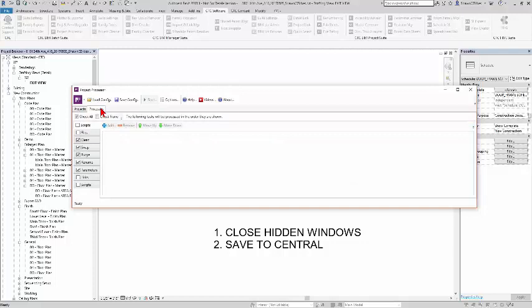To configure the processes here, you go to the Processes tab, and you can go through a number of different options for process configuration. The scripts area here will allow you to run a script before the actual processing is started for each individual model. If you're processing models that are not yet open in Revit, you could do things like maybe deleting files or moving a file to a specific location, whatever the case may be.